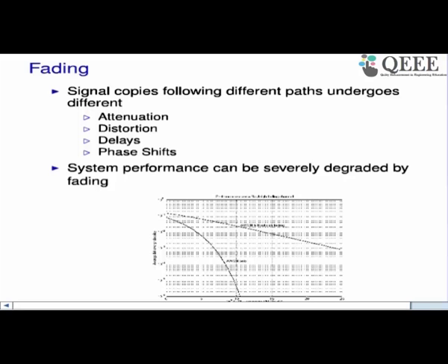So if you divide, 3 dB amounts to basically doubling of the power. Now this is 40 dB. So you divide by 3, what do you get? This 2 power 12 point something times increase in power is required to get the same performance as a wired channel. This is a huge effect.